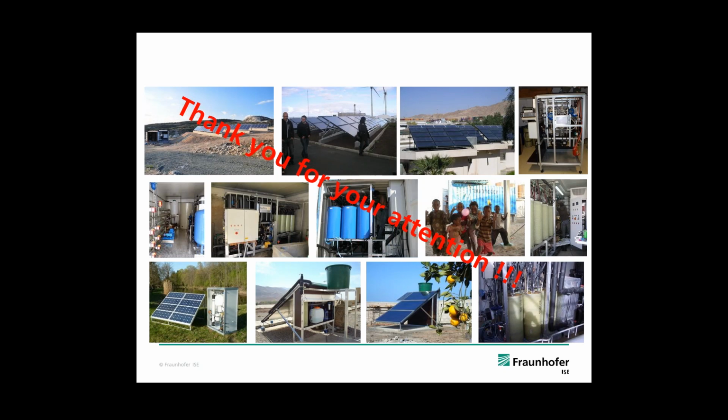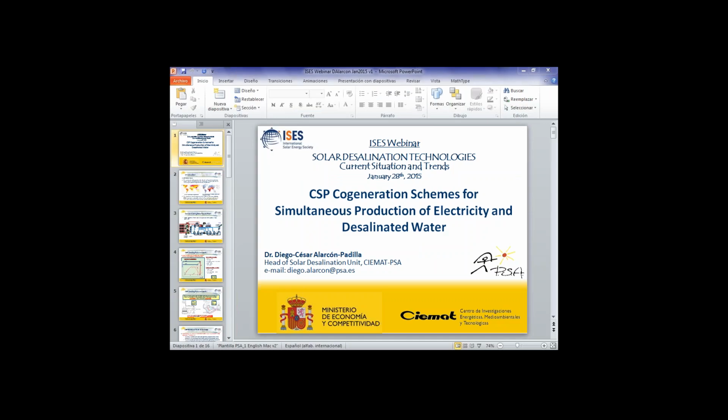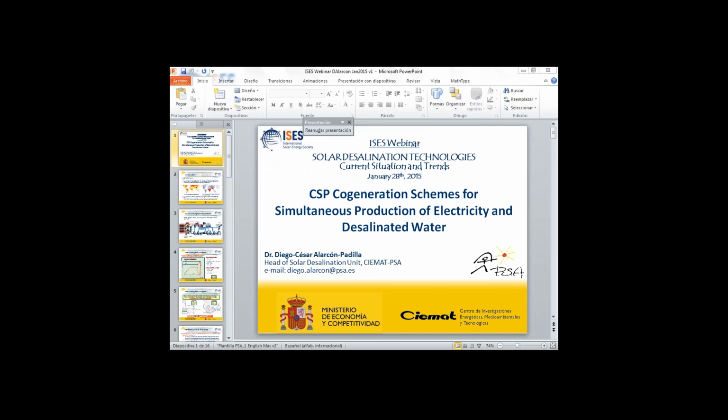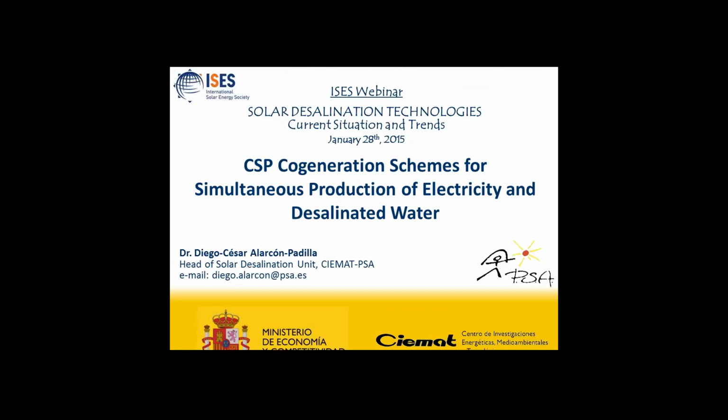As already said, high salinities can be treated depending on system configuration, and it can also be used to concentrate the brine close to saturation, so that it could also be used as a pretreatment step for zero liquid discharge. Basically, the product water is of very high purity because it's distillate, and I think there is a huge potential for cost reduction because all parts in the module are made from polymers. Finally, we can use polypropylene for everything. Polypropylene is quite cheap and can also be recycled.